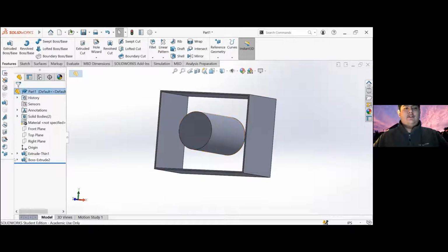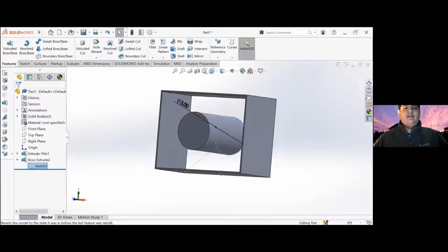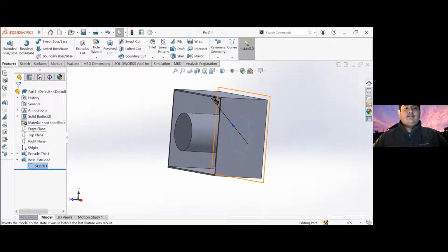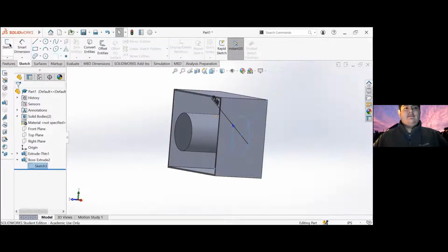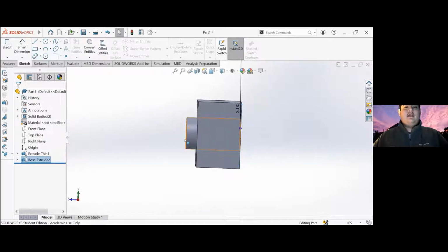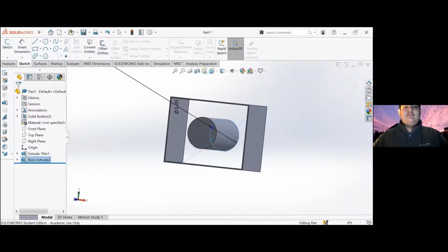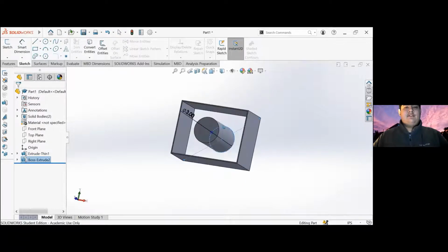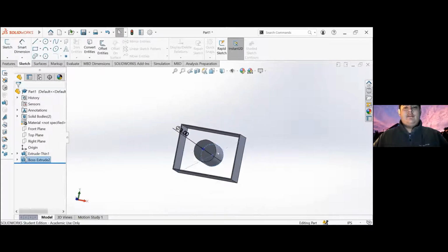And then we started a new drawing, a new sketch on the plane that we literally just select, front plane, and start a new sketch on this plane. And we can start drawing there and just kind of make the shape pop out. And we then extruded the circle. And I just left an offset, but you can pretty much just select whichever dimension you want here.